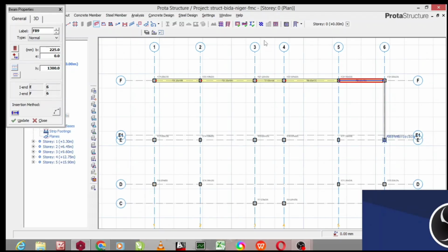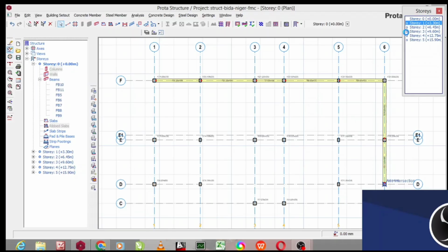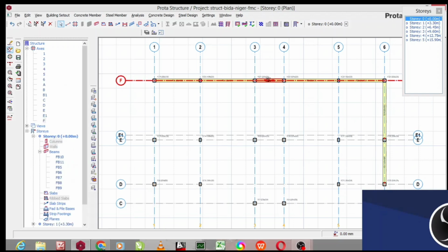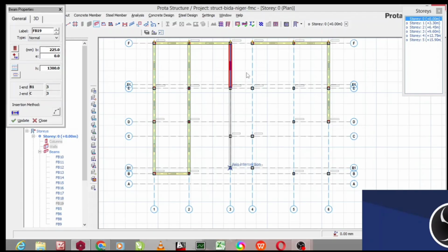If the result shows the soil bearing capacity is very low or very poor, the structural engineer is left with the option of picking a foundation that will be able to carry the structure. The soil on its own is required to resist the load. The load applied should not be more than the resisting force coming from the soil.